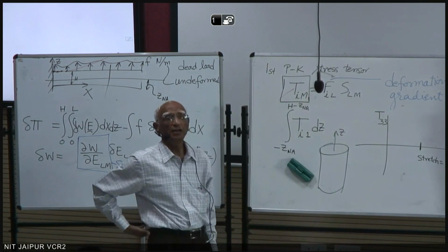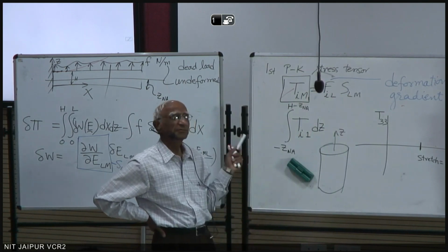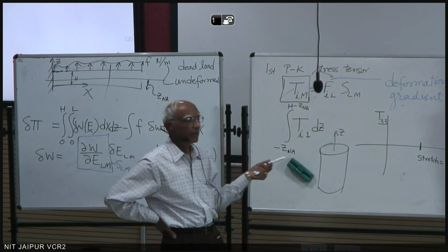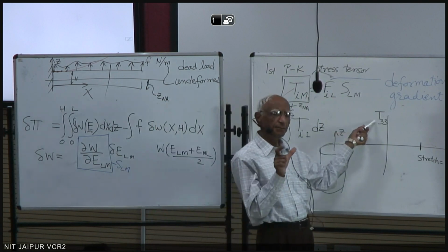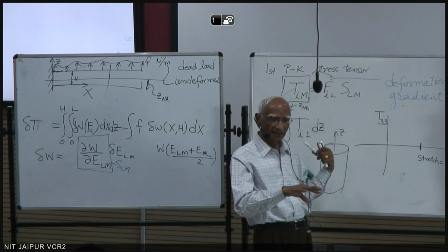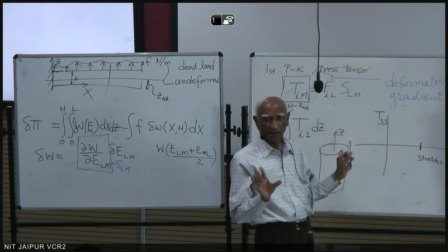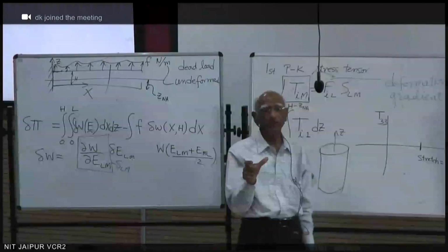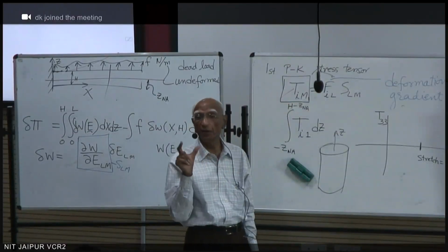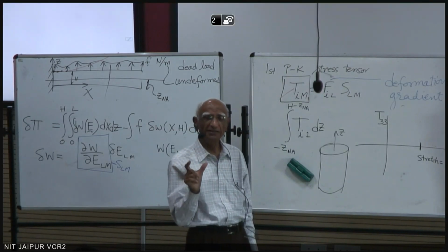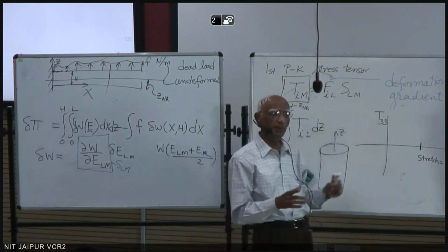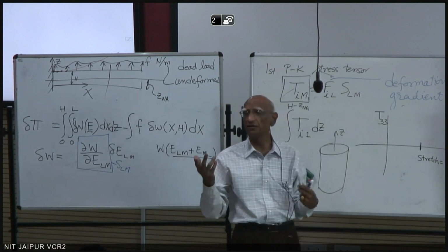So if you plot the axial load, this is present load over undeformed area. So this is proportional to the axial load, because the undeformed area does not change. This is not true stress. This is nominal stress or engineering stress.